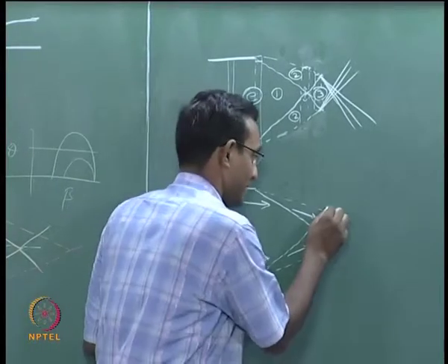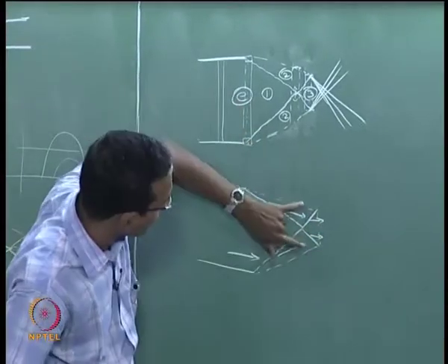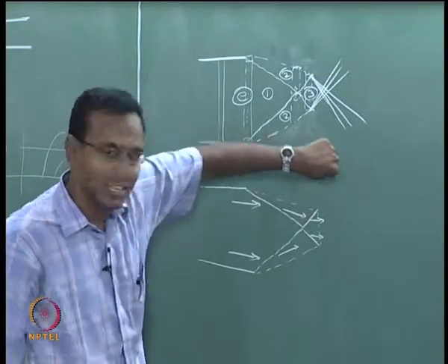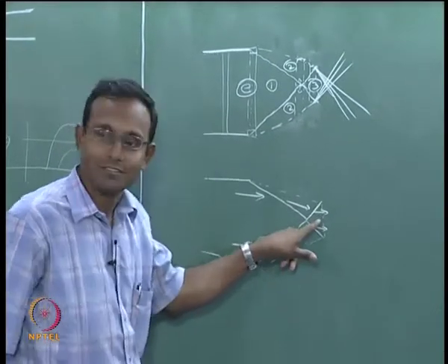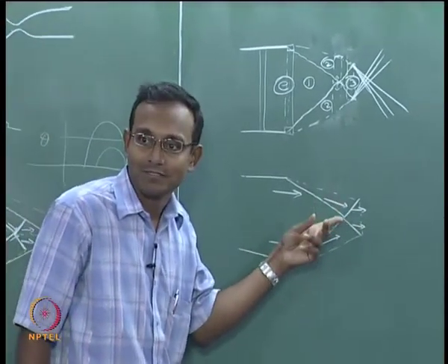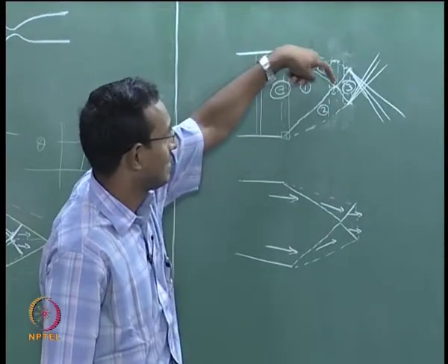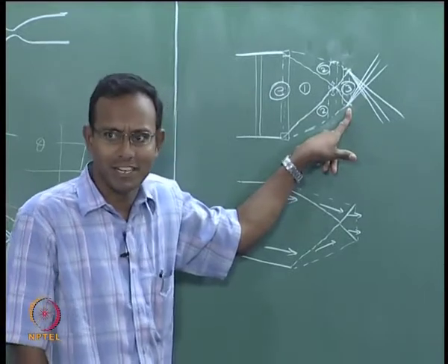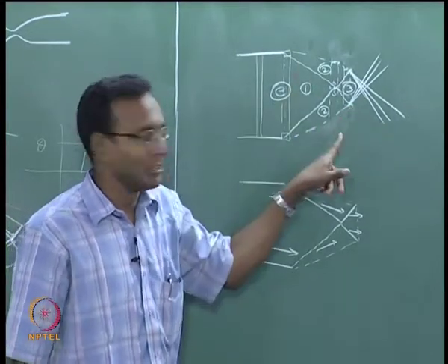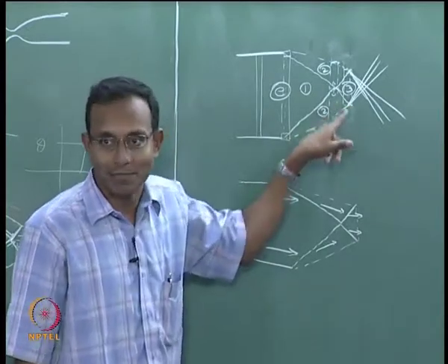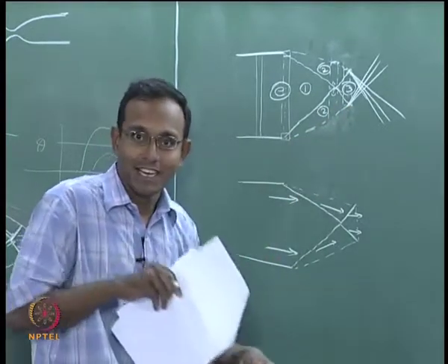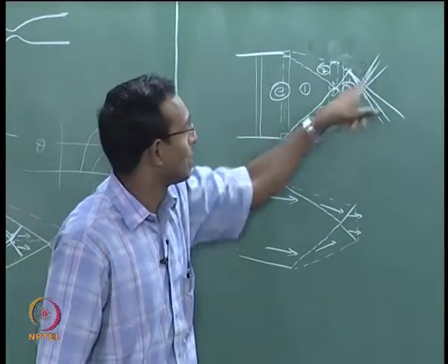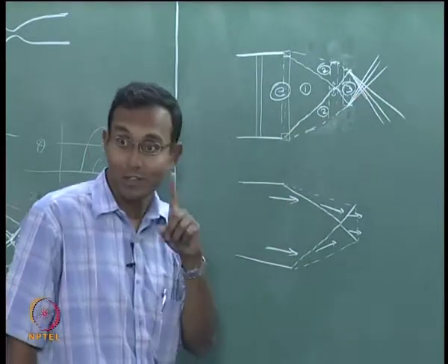And when the jet comes out of this point, the very first point when the jet-like thing comes out, immediately it is seeing that the pressure outside is lower than the pressure inside. That is another way of looking at the same thing. One way of looking at it is, the compression wave comes here and sees an adamant atmospheric boundary condition which says pressure cannot be changed. So the boundary is going to replace the compression wave with an expansion wave at that point, so that the compression and expansion get cancelled. At that point alone they will be cancelling, everywhere else it is going to continuously expand. That is one way of looking at it.